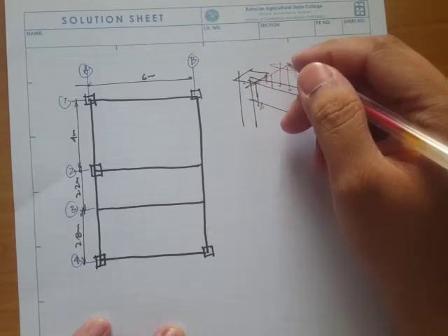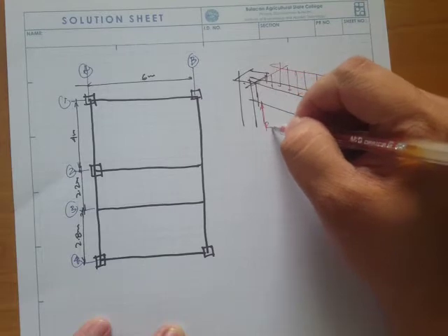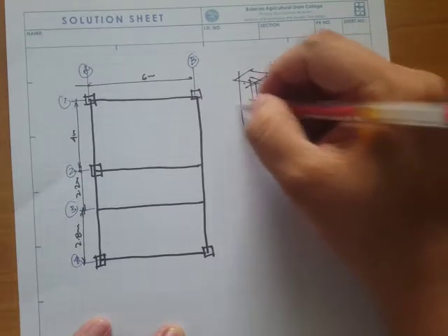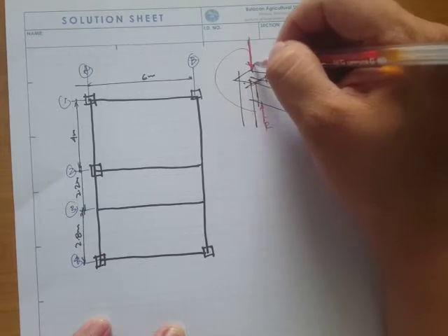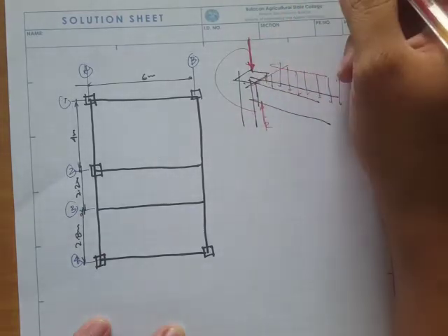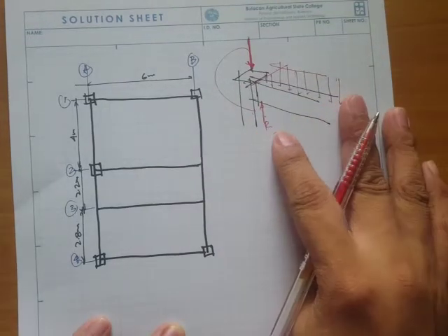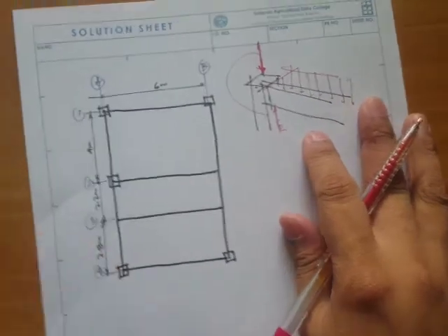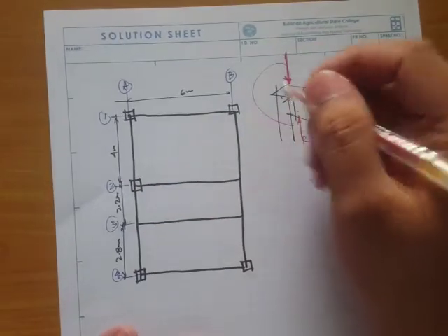If you have a simply supported beam, then you can calculate the support reaction. This reaction is transposed to the column, and that becomes the actual loading for these columns. So that is one way you can solve for that, but there's another way that's more direct and probably easier.